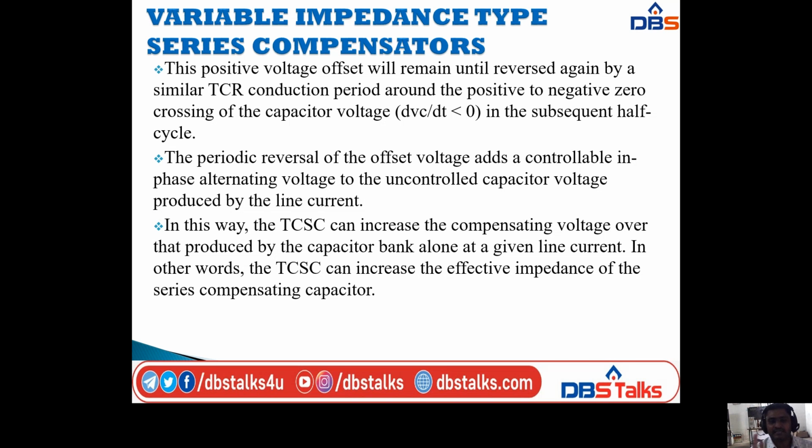In this way, the TCSC can increase the compensating voltage over that produced by the capacitor bank alone at a given line current. In other words, the TCSC can increase the effective impedance of the series compensating capacitor.